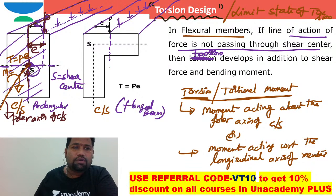Now some people will ask, sir, how do we identify the shear center for this flanged section? Generally, the shear flow is from downwards to upwards in this way. This is the direction of shear flow. If you take the moment of the resultant shear flow about this point, it is zero. So this will definitely be the shear center.